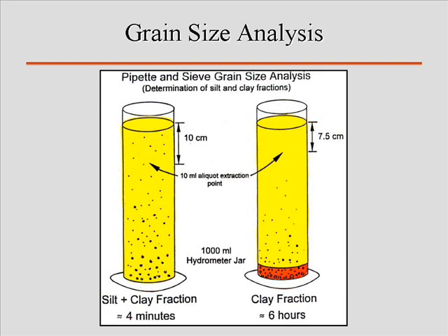All right? Now the trick to this, and the reason why grain size analysis is not exactly dealing with the most ideal situations, is that if we were to take a bunch of sediment and dump it at the top, we would have a problem. Because sediment's going to be a mixture of different grain sizes. If it's dry sediment, it takes a little bit of time for the fine particles to wet, get to the density they should be, to start to fall down. Moreover, they're going to be clumping. So we can't do that. In fact, we have to start off with a wet sample.